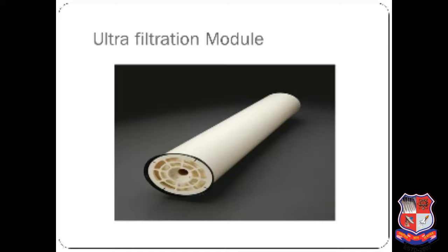Here the ultrafiltration module configuration is a pressurized system or pressure vessel configuration. The transmembrane pressure is generated in the feed by a pump, while the permeate stays at atmospheric pressure. Pressure vessels are generally standardized, allowing the design of the membrane system to proceed independently of the characteristics of specific membrane elements.